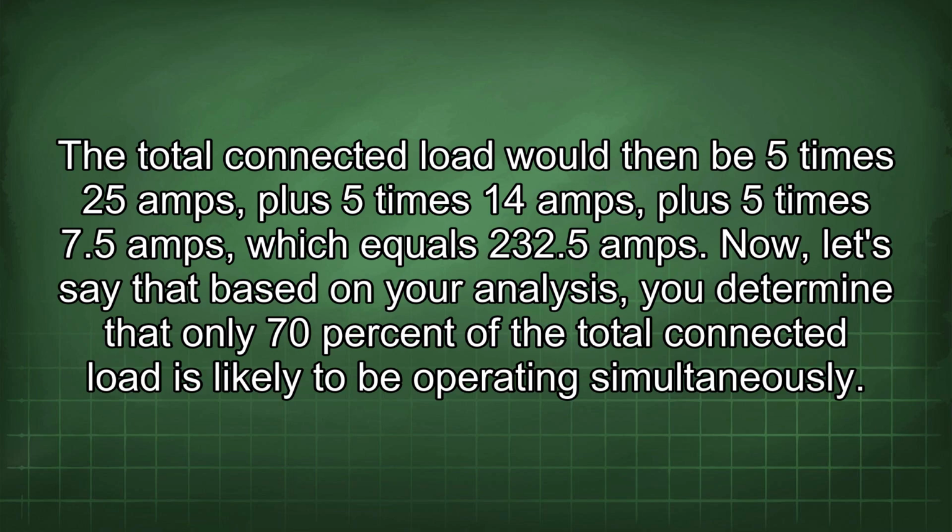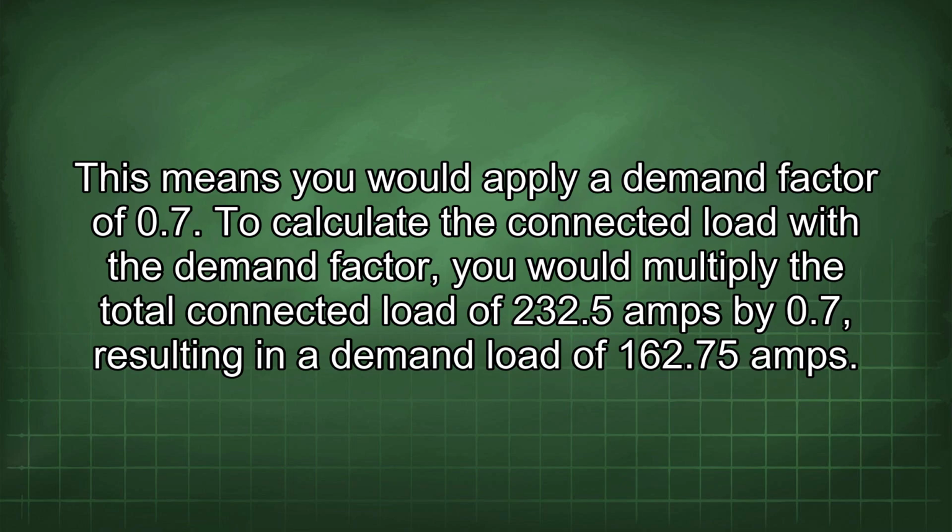Now, let's say that based on your analysis, you determine that only 70% of the total connected load is likely to be operating simultaneously. This means you would apply a demand factor of 0.7.